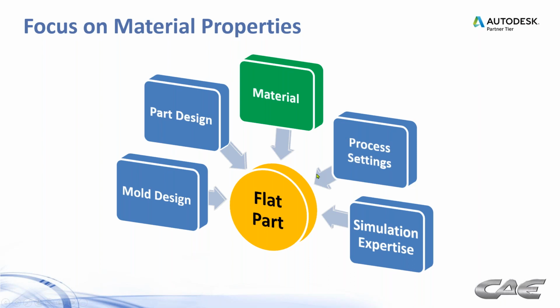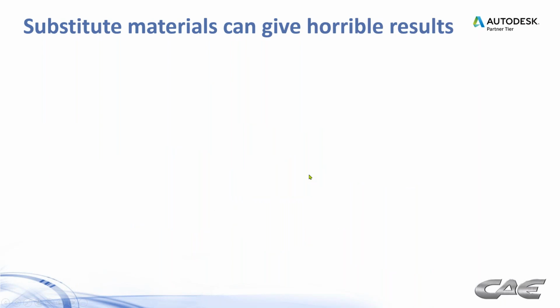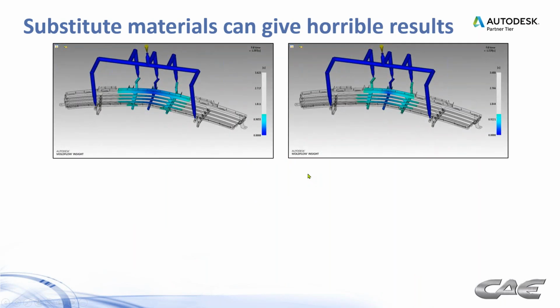We also have material issues, you know, the big one being fiber filled versus not fiber filled. And those are all things that are related to the functionality of the part, right? They have to be stiff for whatever reason, taking on some sort of load. But when it comes to Moldflow, we have to make sure we have good material data in order to be able to predict what's causing the warpage and attack it.